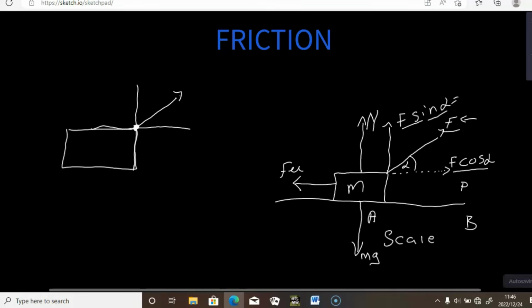So whenever the original force is pointing away from the point, also the vertical component and the horizontal component will be pointing away from this. But take note, you must always remember that from the Cartesian plane, if you are dealing with this quadrant, you are only allowed to use the walls of this quadrant. Meaning, if it's away, you are only going to put it here. Don't say it's away and then put it away and away. Put it here. No, because that is going to give you a wrong direction.